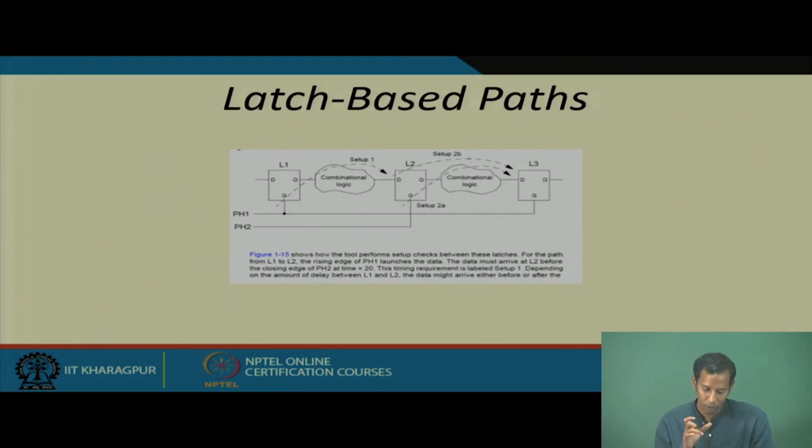So, for the time period the clock is 1, the latch is transparent, that means whatever the data input is will be passed to the output. But whenever the clock is 0, it acts in storage mode, that means whatever the last value it contains, it will store that information only. It will not take any input and pass it to the output.